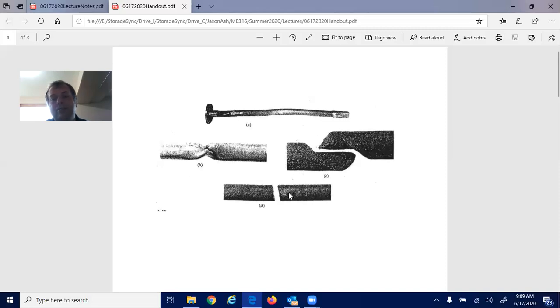And so for axial loading, this would be an example of a ductile failure, where they tend not to have these little marks coming out, but they fail at 45-degree angles. They'll usually kind of neck down and then fail at a 45 if it's ductile. And then if it's brittle in axial loading, it'll fail at a 90-degree like this due to the maximum normal stress.